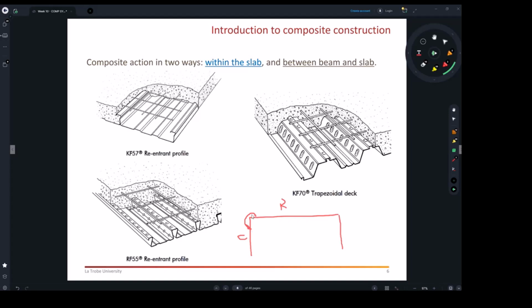No. Composite when you have one member, one element, right, built from two different materials, and that was not the case here. Then, like the column and the pad footing. But still, the column is our element, and the pad is our element by its own. I know where you're coming from, but no, you won't call this. You just call it a portal frame because we have managed to connect it with all those full fixity connections. When you connect things together with full fixity connection, it does not mean you are making them in composite.